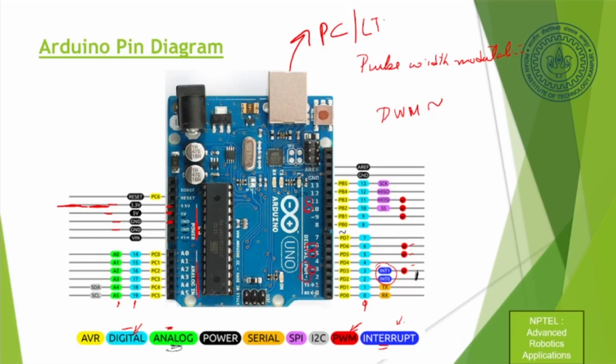So what we can see here is, number one, there is a reset. There is a physical button here. There is a physical button which is a reset pin. So if you press it, whatever is running will get reset immediately. Okay. There are also LEDs. So there are lights here. This is a power light. Okay. And there is one here. That means the moment you connect it to the PC, this will start glowing, indicating that it has made a connection with your PC. Okay. And the PC is giving it the power through the USB connector.